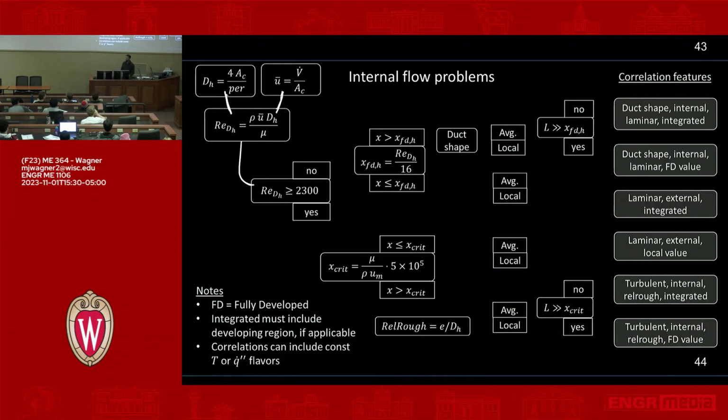You can make some determination about whether or not that Reynolds number would lead to laminar flow or would lead to turbulent flow. Right? And remember, if it's going to be turbulent, it has to do so before that fully developed region. If we compute that the Reynolds number is greater than 2300, then it will become turbulent before that point.